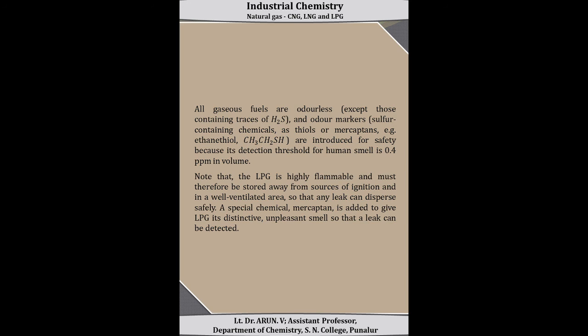Note that LPG is highly flammable and must therefore be stored away from sources of ignition and in a well ventilated area so that any leakage can be dispersed safely. In the case of LPG, a special chemical called mercaptan is added to give LPG its distinctive unpleasant smell so that any leakage can be easily detected.